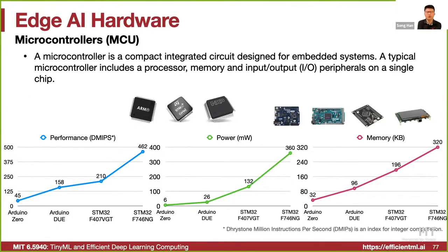And there are also microcontrollers for many IoT devices, like a smart home camera might have one of these small ARM devices, just a couple of hundred milliwatts, but the memory is also super small, just a few hundred kilobytes of SRAM, maybe a few megabytes of DRAM, or even no DRAM. Some microcontrollers have completely no DRAM. We have to manage the memory super carefully.